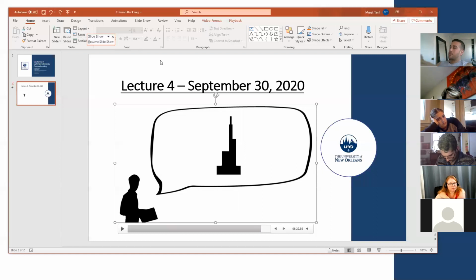Or you can look at this one, if you change the orientation, as a cantilever beam. Instead of this high-rise structure, I change the orientation. I have fixed at one end, that's a cantilever beam, and I'm applying a point load. It's going to create a moment right here. This is a basic static problem that you solve, and then you can size your beam, you can size your column. The column design is similar to beam design. It all depends on how you picture it, how you look at the orientation.